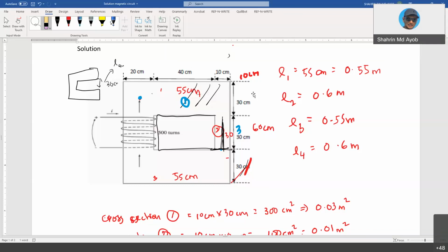For the source with unity power factor, Q must be 0. So what do you mean by the power factor? You mean the power factor of the source. If the power factor of the source is unity, meaning that the voltage and current of the source are in phase, yes, the Q will be 0.